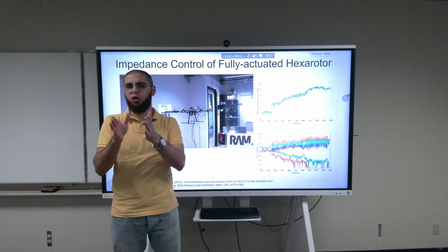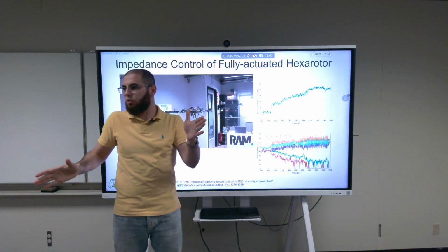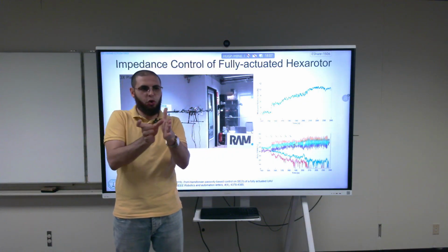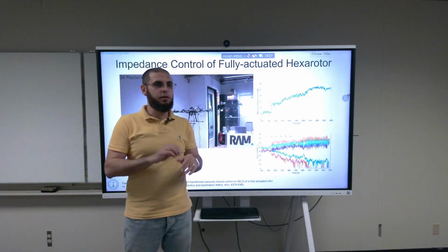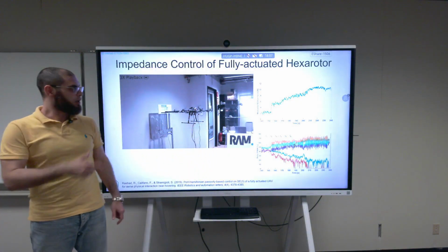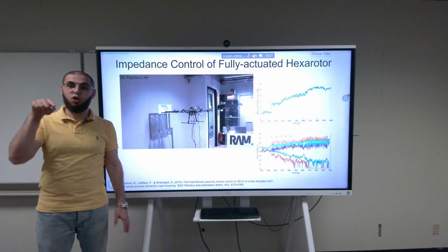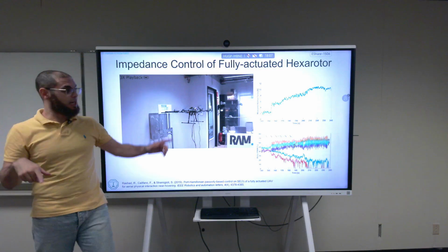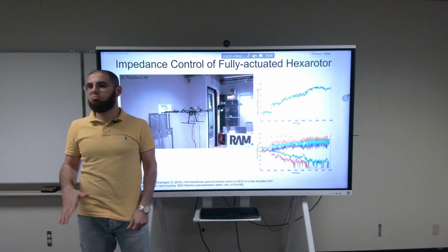It's not like I can continuously control them from 1,000 RPM down to 0. At some point, for example, from 200 or 300 down to 0, it's all 0. It needs a little bit of a push. Even this dead zone is another source of disturbances. What about the performance? It's actually during interaction. So it's still applying the force, and at the same time, you've reached the limits, and what's happening? Nothing.